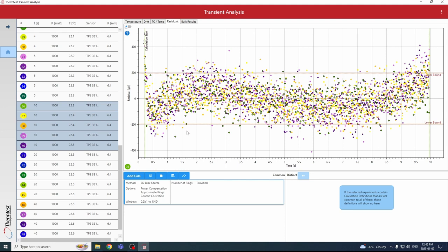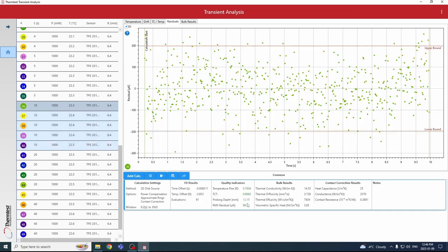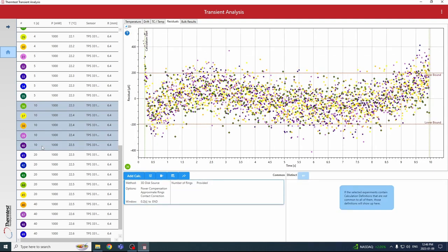We can investigate that by looking at the 10-second measurement that we identified as ideal for this stainless steel sample. Again, we want to select test times that are maximizing the available dimensions but not penetrating past them. So in our 10-second measurement of this stainless steel, we're probing 12.19 millimeters. And if you remember, we calculated a maximum allowable penetration depth of 13.6 millimeters. So that is why our residuals are random, as we have not hit any edge of the material and reflected it back.